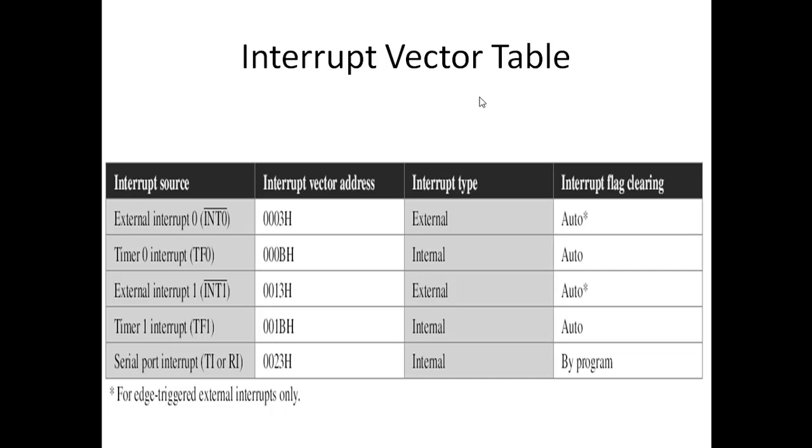Okay, so let's get a concept of what happens. Suppose an event occurs outside and my peripheral wants to inform my microcontroller that the event has occurred, and it sends that signal on the external interrupt pin INT0. As soon as my microcontroller receives this external interrupt, what will happen? Think everything properly, right? It will suspend the execution of the current program and provide service to external interrupt 0. Now what task has to be done?